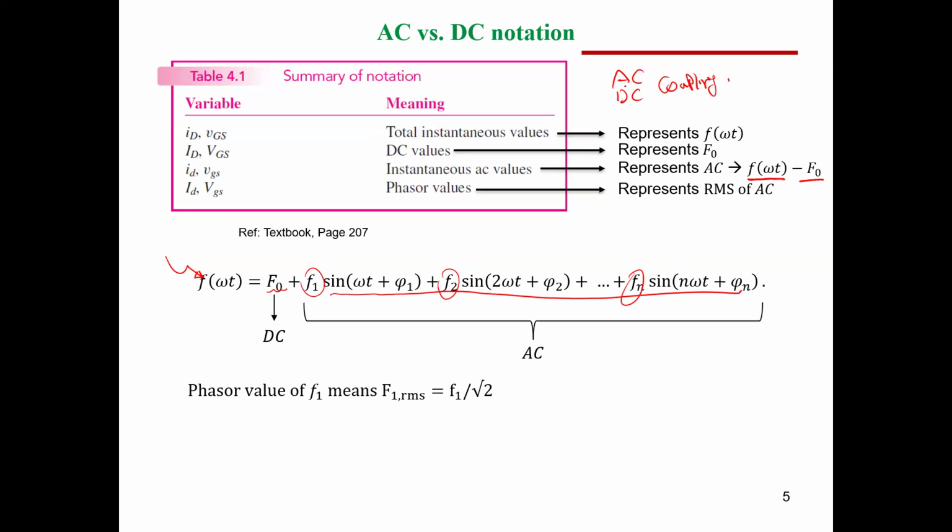So we can use AC coupling in oscilloscopes to see the waveform ripples, which is the AC component of the waveform. Okay. In our analysis today, the AC component represents the AC signal that will be amplified. And the DC component represents the DC biasing analysis, or the components or parameters that we design in order to identify the operating point, which is the DC analysis we made before. Okay.